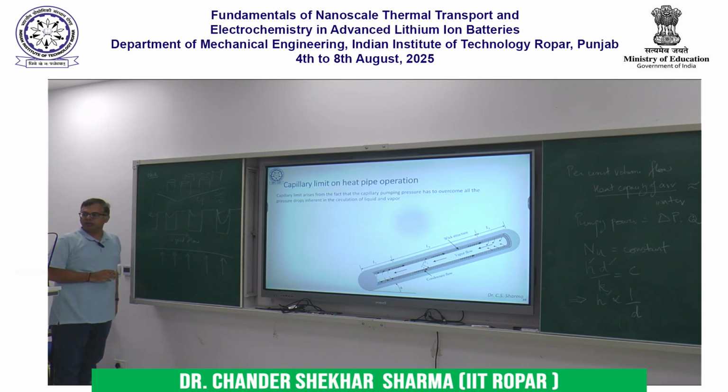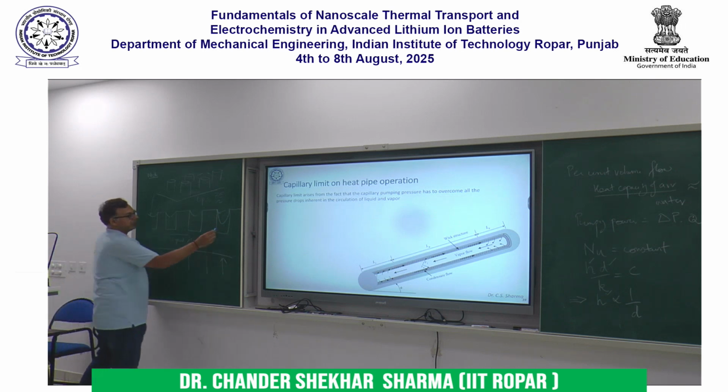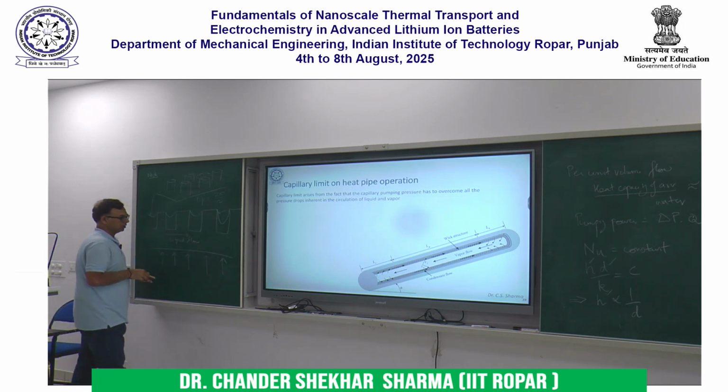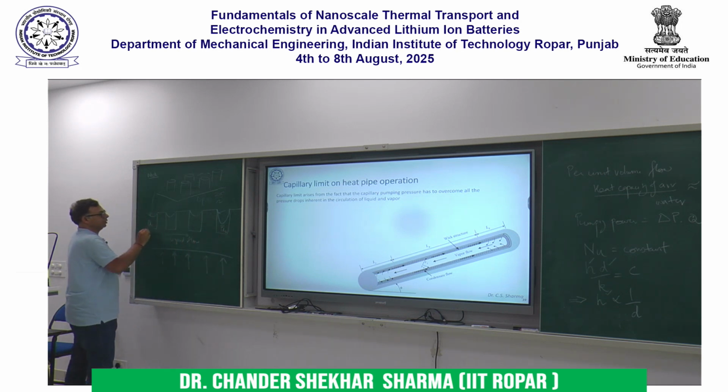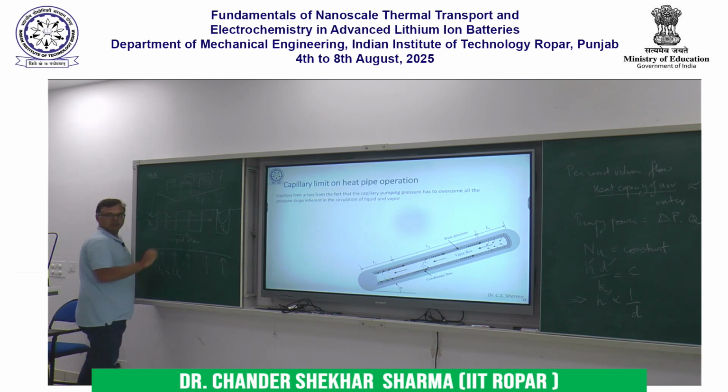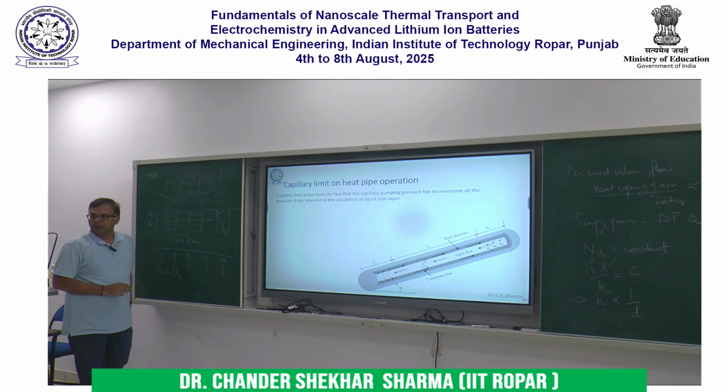So this means that here the liquid pressure PL2 is less than PL1, and so there is a pressure gradient. This pressure gradient is going to drive the liquid flow in this direction, and this is called the capillary pumping pressure, whatever that net pressure difference is.